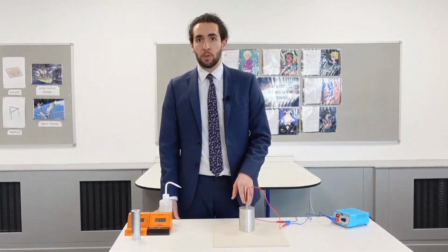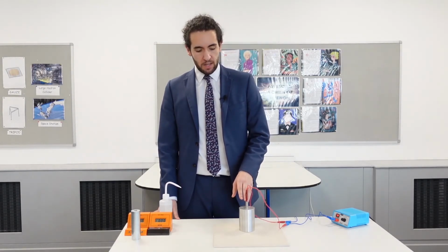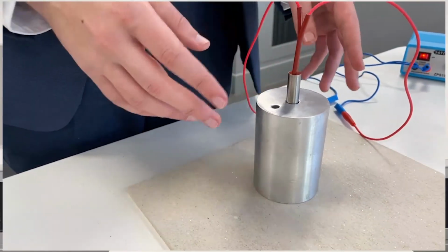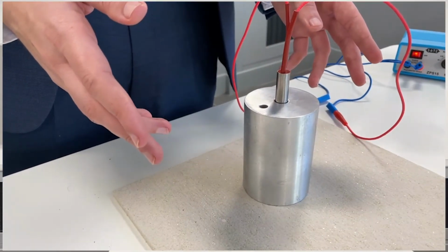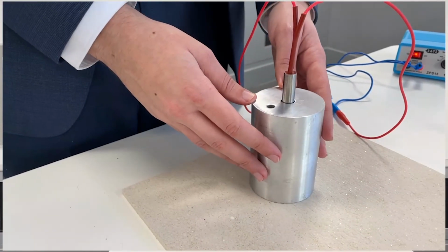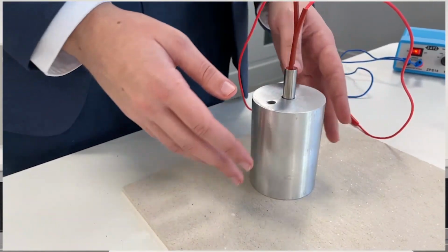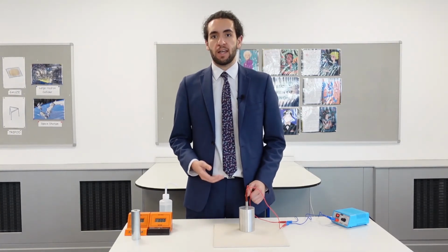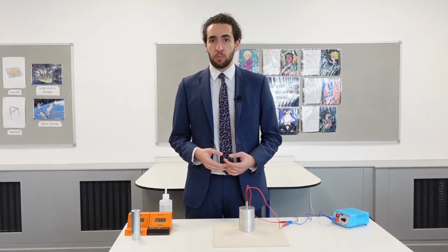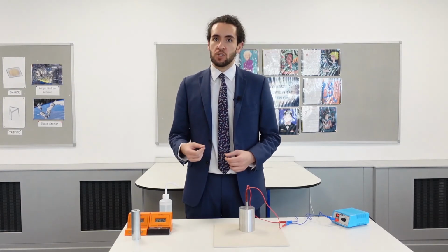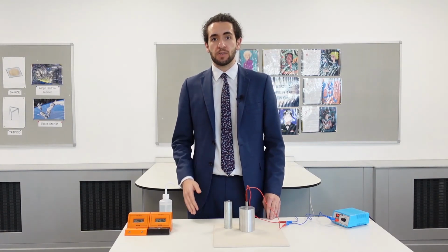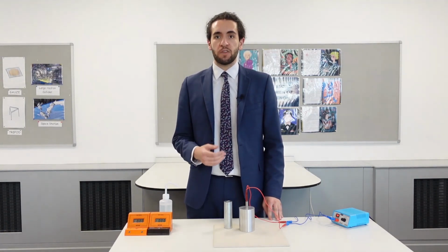Looking at the block here, you can see that the cylinder is not completely within the metal block. Therefore, some of the heat from the cylinder is radiating outwards straight into the air. Another reason, of course, is that the metal block is also radiating heat out into the air. And therefore, one way that we might make this more accurate is to wrap the whole thing in insulation, keeping all of the energy transferred to the block inside the block, or as much as possible. Following this procedure with other metal blocks, I could compare different metals and see which requires the most energy in order for the temperature to be increased.